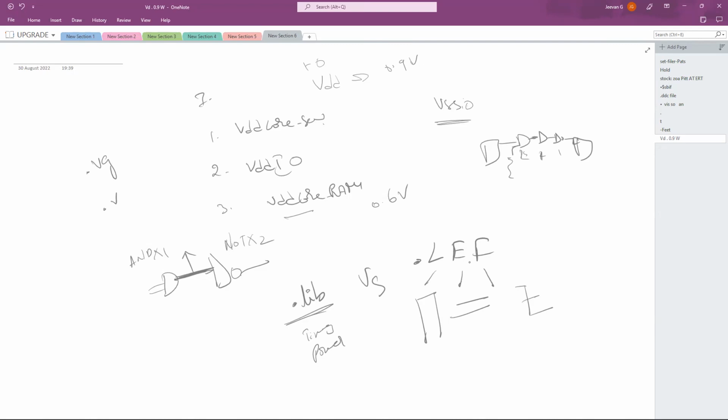Okay, why are you getting a transition violation? Because this is taking more time compared to the ideal time. Why? Because this is being driven by a small-sized buffer. Somehow it manages to drive this, but the signal is not able to move from the AND gate output. This should take only 1 second, but it is taking 2 seconds.